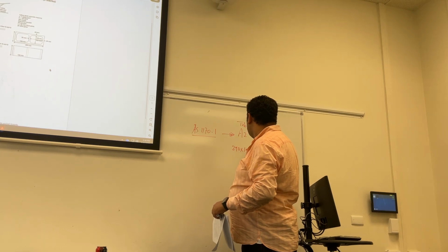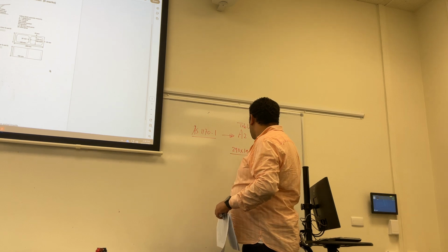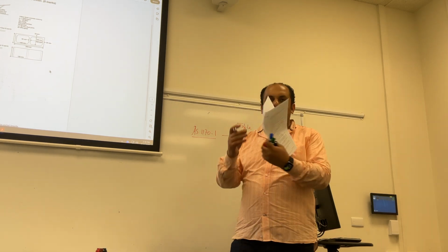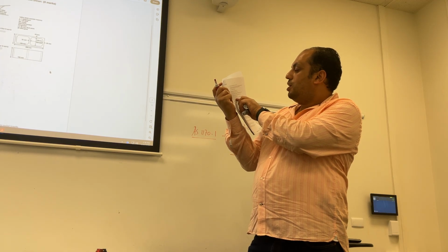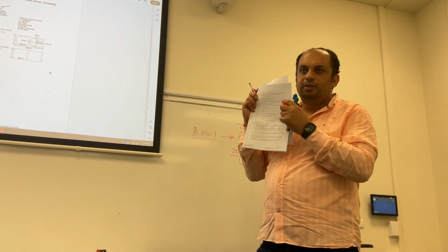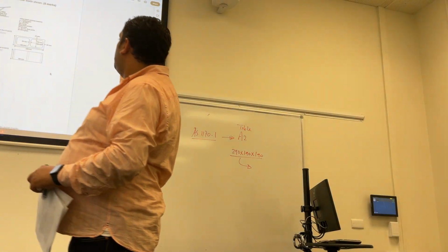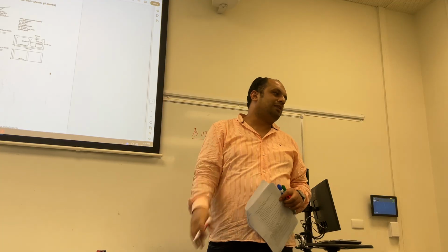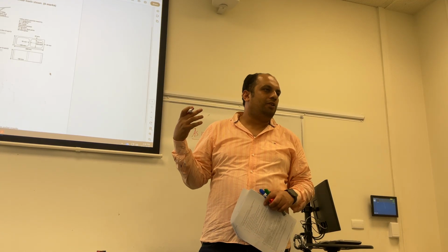190 times 190, right? So here the standard mentions the density of the units, not the density of the whole masonry. There is a difference between the masonry and the unit. Unit means the block itself without the mortar. But this value, 2,200, is for the masonry as a whole. That's why in the solved example we did before, it was.